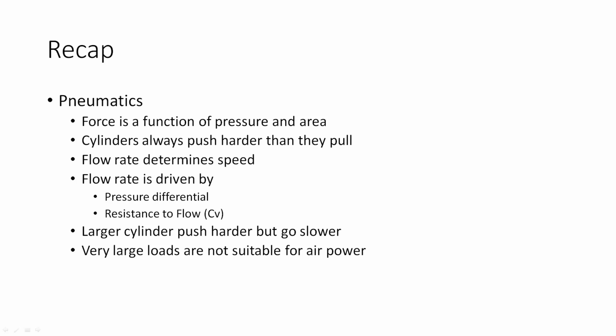The third takeaway is that the flow rate determines how fast the piston moves. That flow rate is driven by the pressure differential. So is the piston loaded or not? Does it have a flow restrictor in it or not? And then the resistance to flow. How big is the valve? Bigger valves allow more flow, allow faster movement.